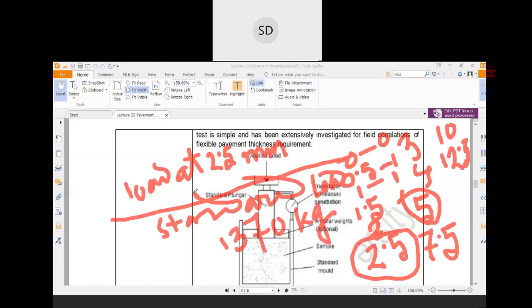Now again you have to find the CBR value corresponding to 5 mm penetration, and for 5 mm penetration the standard load reading is 2055 kg. And you need to tally both readings. Generally it is expected that the 2.5 mm CBR value would be larger than the 5 mm value.